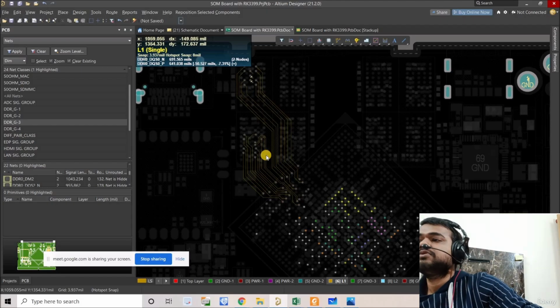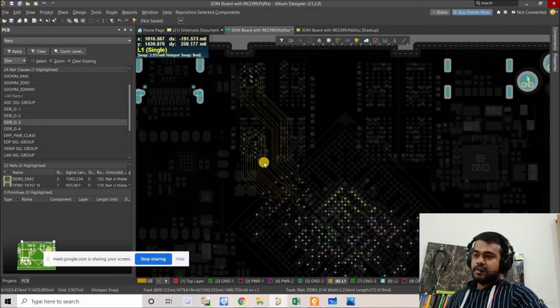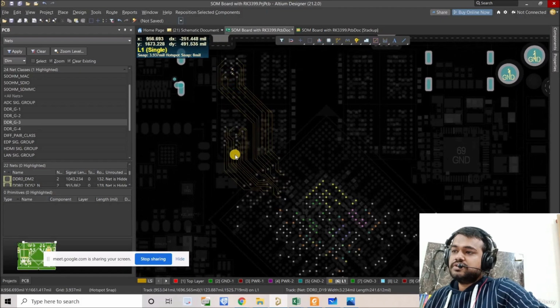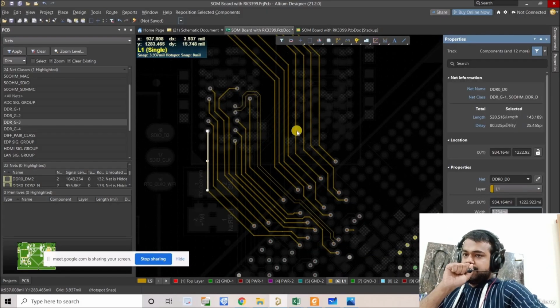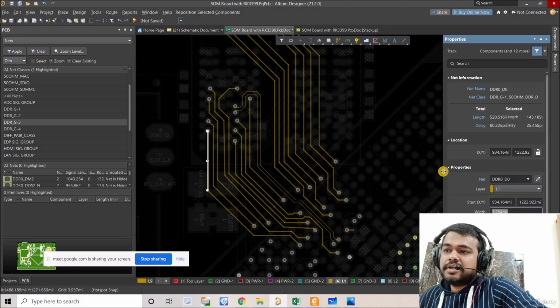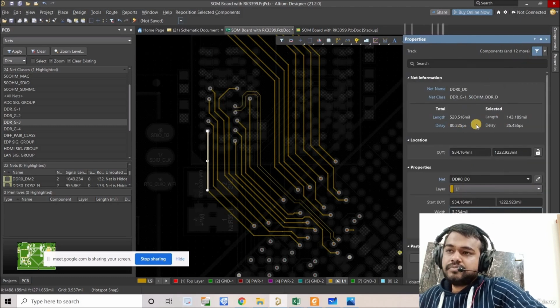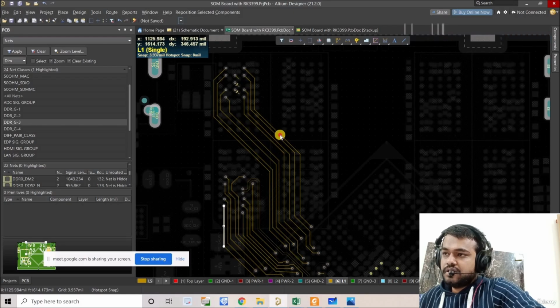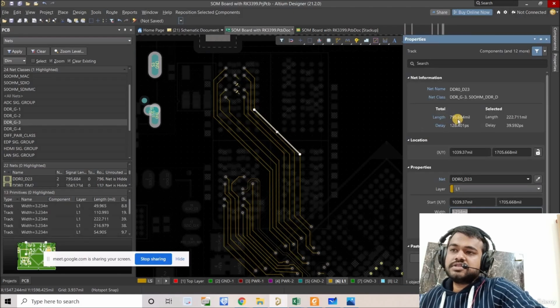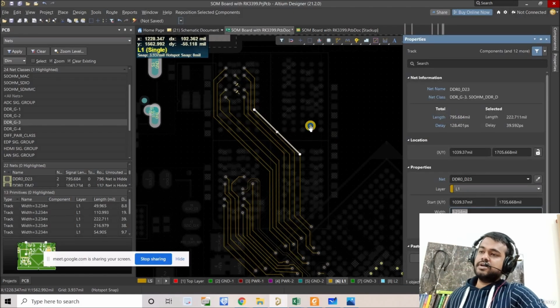Yeah, so I was saying, these are the smaller connections, right? So if you double click on this one, sorry, you can see the maximum length of this connection, so this is the length selected, and this is the maximum length, which is around 520 mil, right? And if you see the length of these tracks, double click on this, it is 700, around 200 mil extra, right?